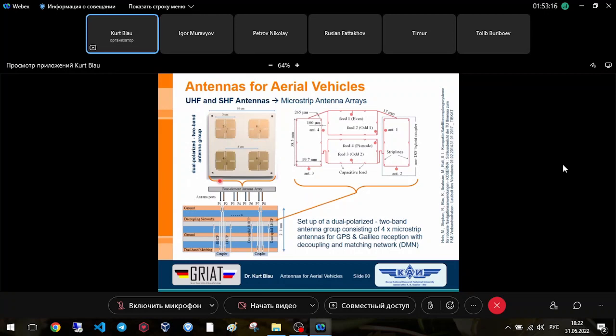And the antenna here is a dual frequency element. Let's assume it's a single patch element without the slots. The slots and these T-like structures make the single patch work for two frequencies. But the principle I want to explain is only valid for one frequency.